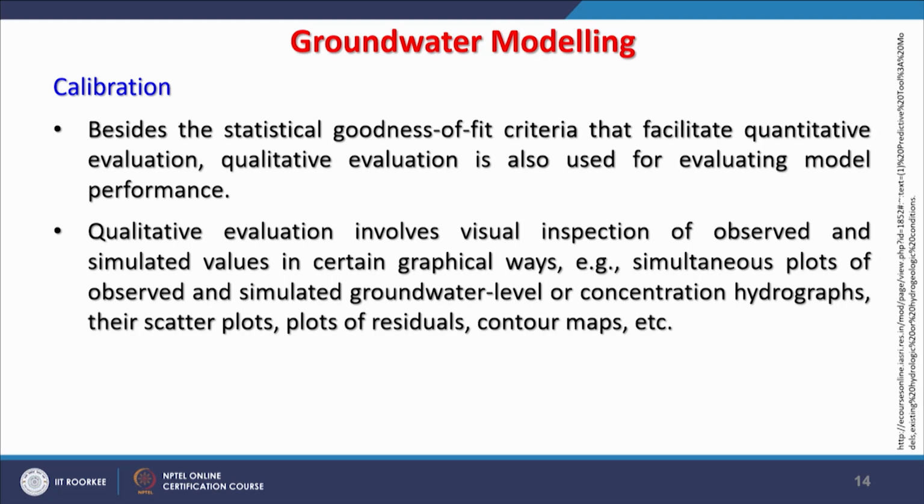That means one can plot the data and then see where the variations are coming between our simulation output and the real values. So, for example, simulation plots of observed and simulated groundwater level or concentration hydrographs, scatter plots, plots of residuals and contour maps etc. can be prepared for the purpose of qualitative evaluation of the performance of a model.